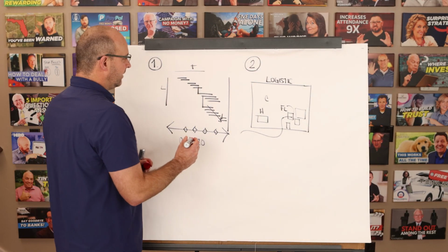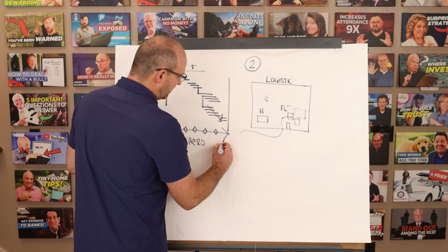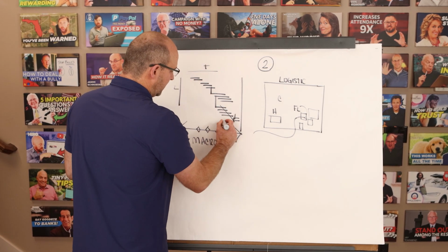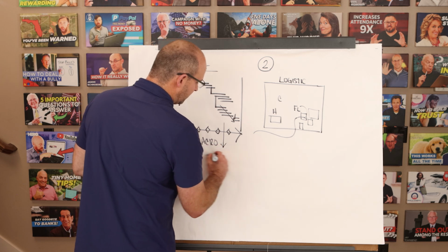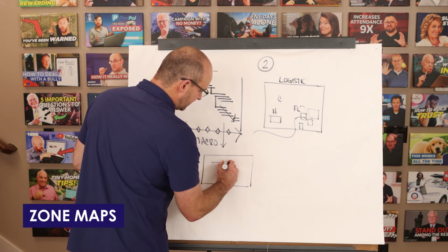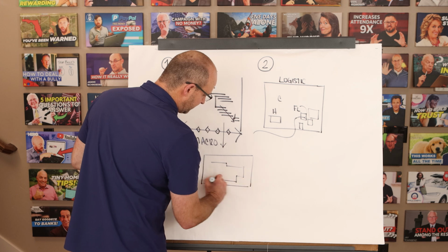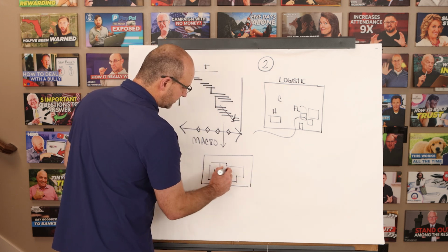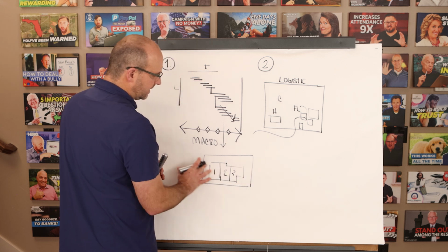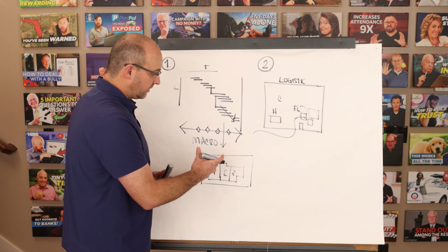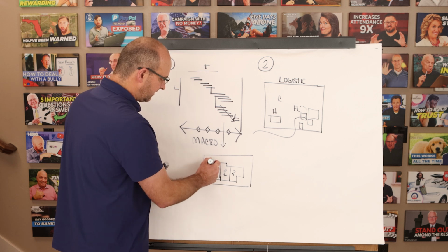Once you have the basics of your plan, and I will add on here another one, is that in your macro level takt plan, you'll also have your zone maps. So let's say, for instance, that this is your building, right? What is the zoning strategy? Zone number 1, 2, and 3, let's say by floor. And this could be in an axonometric 3D perspective as well if it's more complex.